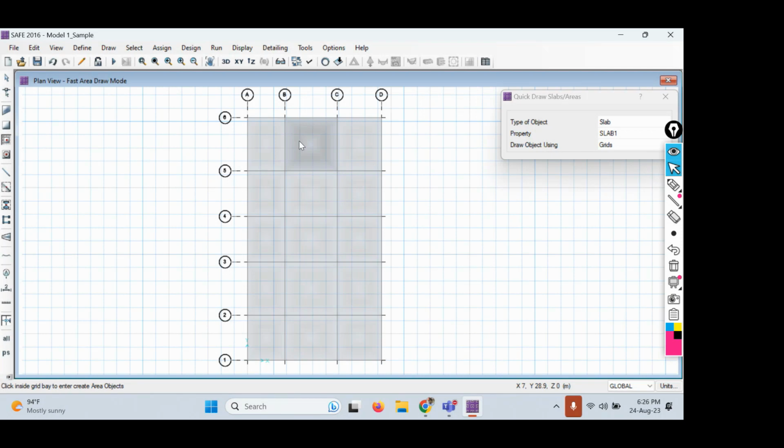If you select this one, have I selected this one? No. So why is it not selected? Because the command is still in the enabling state. Now, how to disable the command? Just click on the select object arrow on the left pane. So select this one. Now the command has got disabled.